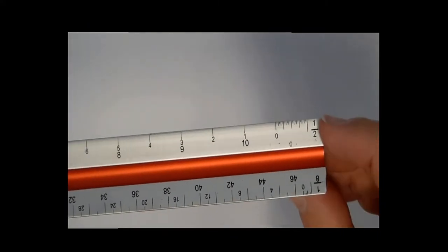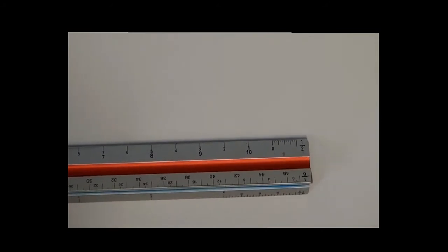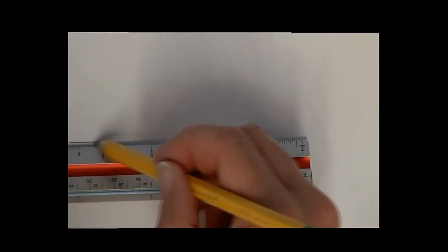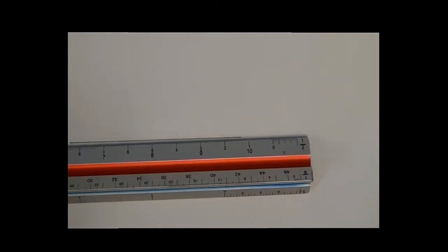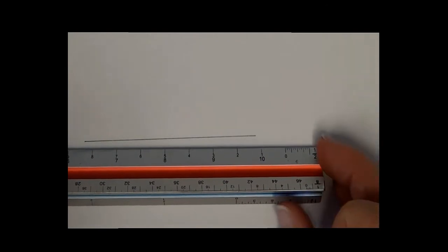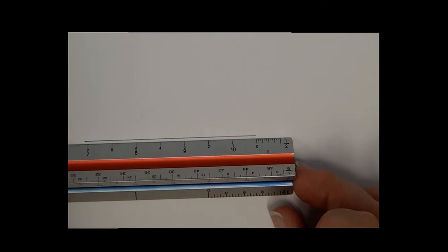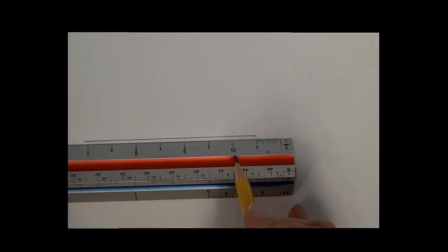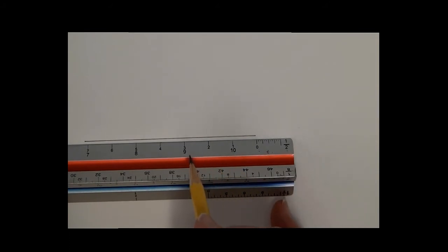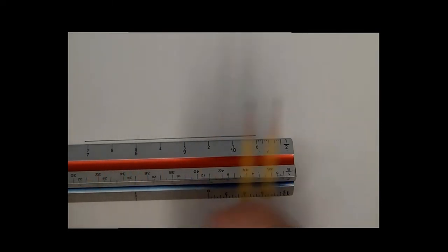So I'm going to flip over the camera and I'm going to draw a little bit of a line here, and we're going to go ahead and measure it in 1/2 inch scale. So what we would do is move it down to the 0 on that 1/2 inch scale. You don't want to include the inches when you start, and then you just count 1, 2, 3, 4, 5, 6, 7. So it's 7 feet plus a little bit at the end.